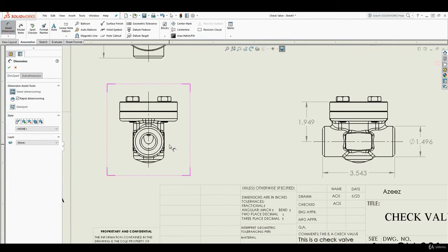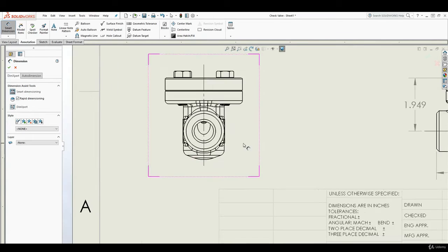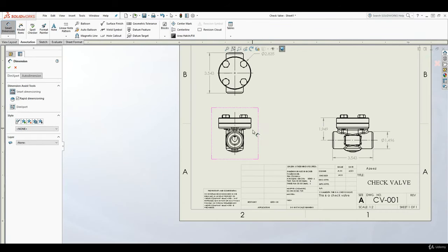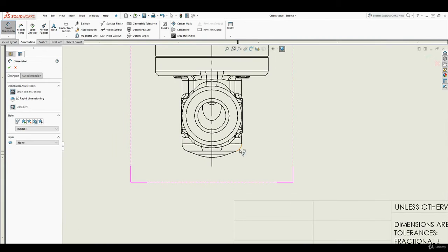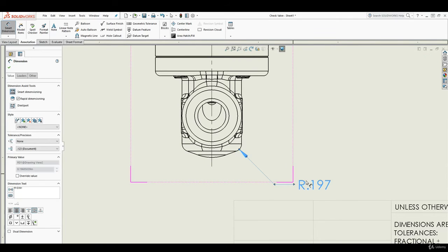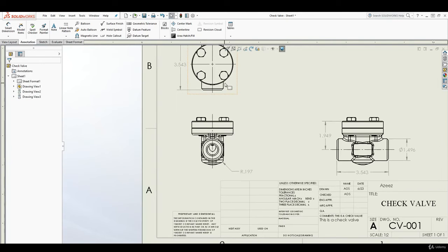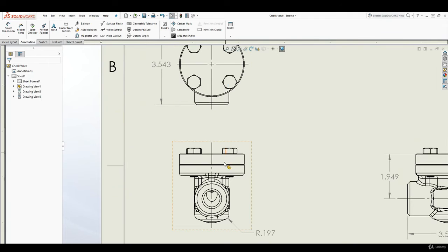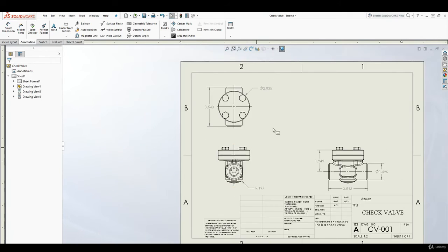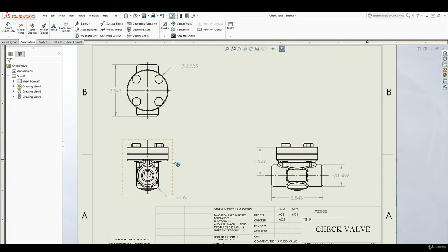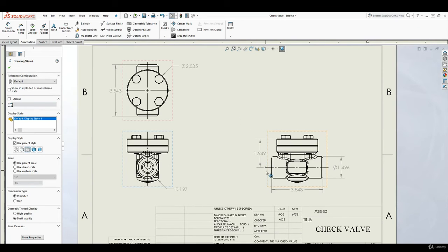So the way SolidWorks works is, sometimes when you click on radius it might not work. For the most part, you just click on the ones that do work. So we click on this radius, and some radius you might just have to add it with notes. So we click on this radius, and any part you click on, SolidWorks is actually going to be able to recognize whether it is a diameter or just a straight part. So anyway, that's how you add your dimensions, by just clicking.